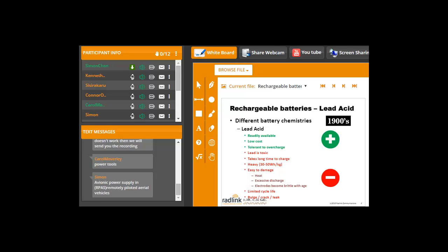So what you do is you have a constant current source providing power into the battery at 2.4 amps up to that 4.2 volt limit. At which point you have to switch from constant current, you've got to reduce the current and switch to just constant voltage and charge it at 4.2 volts. These cells can discharge up to 1C, so again 2.4 amps, but you must not discharge them below 2.5 volts, because below that voltage, the cell's chemistry changes and you'll no longer be able to use it.